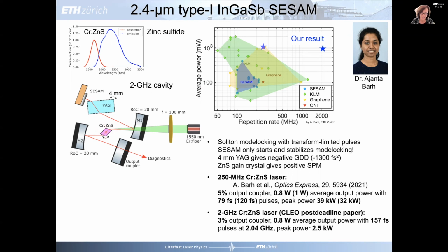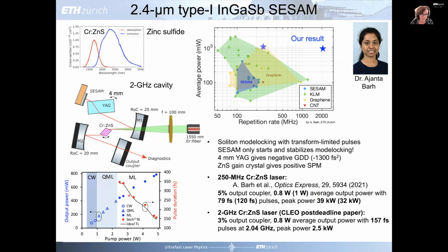So you have, again, soliton mode locking, which also places a requirement on the saturable absorber. So it's not a hard test on the saturable absorber, because we got it going with both type 1 and type 2 SESAM, which is interesting. The type 2 SESAM would not work in the VECSEL. But it was really nice that we could show this improvement, and that, again, the mode locking is really done by soliton mode locking, which you can see.